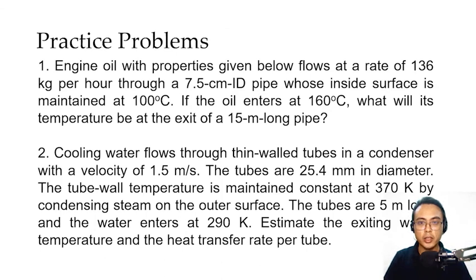And finally, here are some practice problems that you can solve on your own. You need to take note that in these problems, the exit temperature of the fluid is not given. So you would first need to assume an initial value of the exit temperature, solve the problem, and then determine the exit temperature through our equation Q is equal to mc delta T is equal to HA delta T. These problems are iterative in nature. I will be posting separate solutions to these practice problems, so please watch out for that.